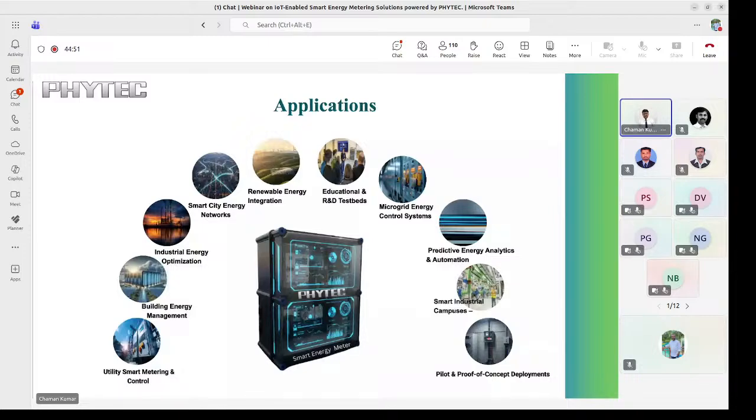Okay, so as you see here, we have a dashboard. This is our basic setup kit, where we are reading the data from the optical meter reader. This is our OMR. Right now I am not going for the RF mesh. First we have to read the data from the OMR itself. From the OMR I am reading the data, and on the back end I am running Google's DLMS Director SDK, which will get the data and send it to the dashboard.